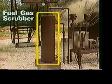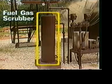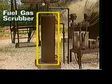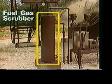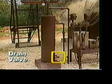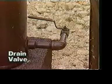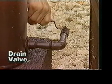The fuel gas scrubber prevents entrained liquids from passing into the burner along with fuel gas. Should the scrubber become filled with liquid, a float rises and shuts off a valve. This stops the flow of gas to the burner and prevents the possibility of fire. A drain valve is fitted on the scrubber to remove collected liquids. A pumper should check and drain the scrubber every day.